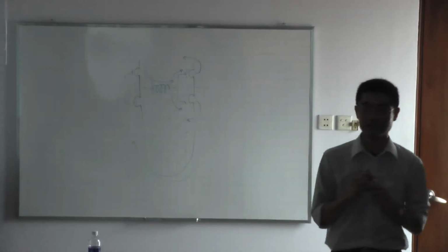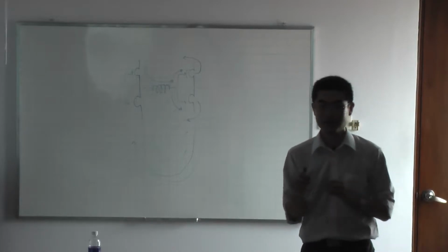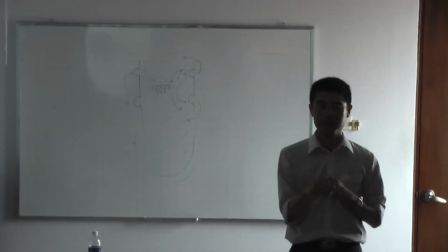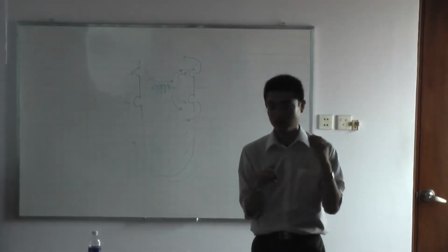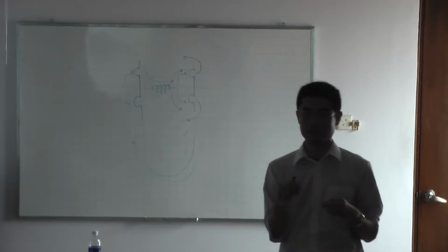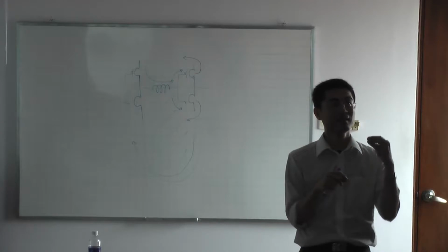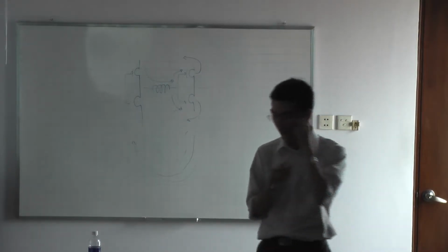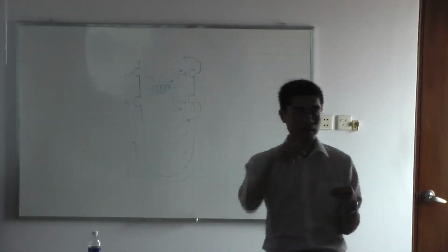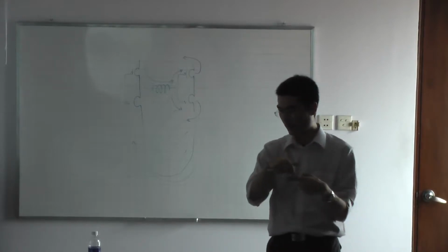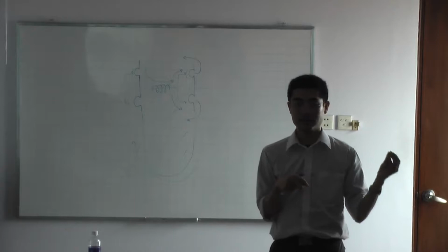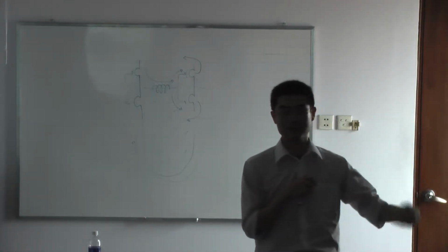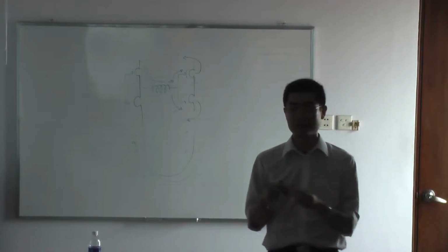And the other one is the bias T. This has the reverse function of the blocking capacitor. The blocking capacitor removes the DC component, and the bias T adds the DC component. For DC, L is short and C is open. And for AC, C is short and L is open. So with this kind of connection of C and L, like a T shape, we can add a DC component onto the incoming AC signal. The input is AC, whose DC voltage does not matter, and the output is the incoming AC component plus the applied DC component.